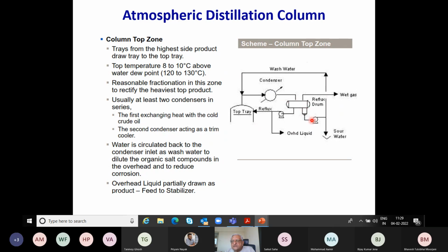It is just a kind of cylindrical vessel which is welded onto the bottom of this. So it's a vertical vessel welded onto a horizontal vessel, so that we keep the water separate from the hydrocarbon. Then part of the hydrocarbon is refluxed back, the same way that we had studied earlier, and part of it is withdrawn as a product.